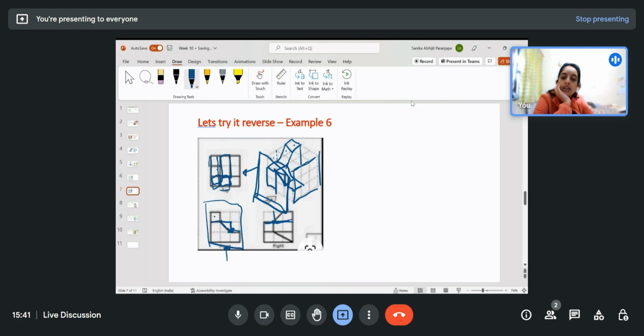So now in right hand side view, that is when you're viewing from here, or in this figure you're viewing again from here, right hand side view, you can see that there is a slant over here. So that slant will be visible in the top view, that is this slant. This is this slant that I'm seeing. So I have already drawn this cube looking at this figure, and now I will join this slant.